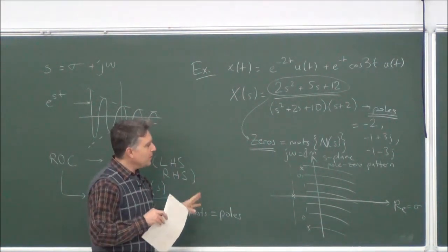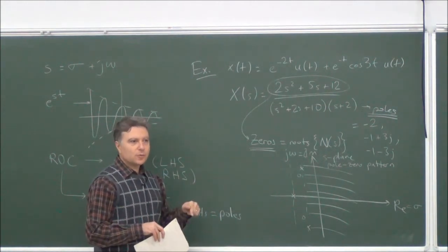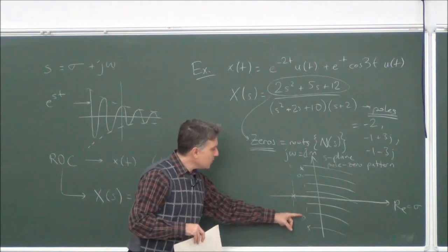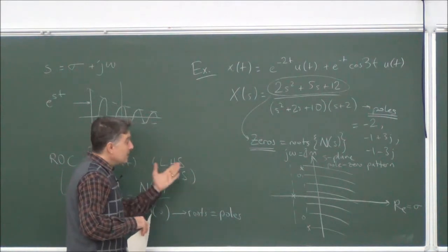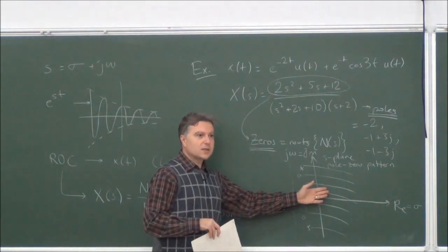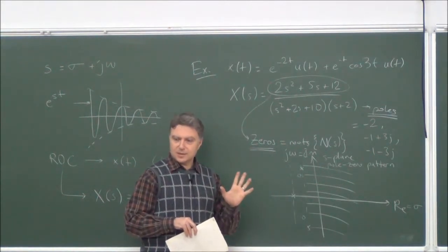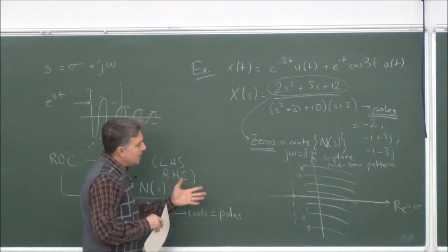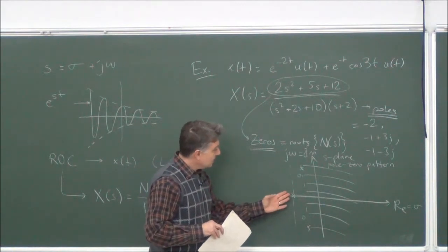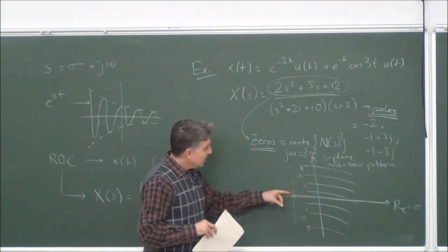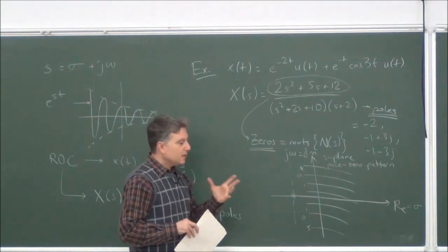In order to have a complete S-plane representation or pole-zero representation, you are required to indicate the poles as well as the zeros. However, the zeros may be inside the region of convergence. Inside the ROC, you may have some zeros. It's not a problem, that's no big deal. In the books, the pattern is usually plotted like this: poles with small crosses, and zeros with small circles.